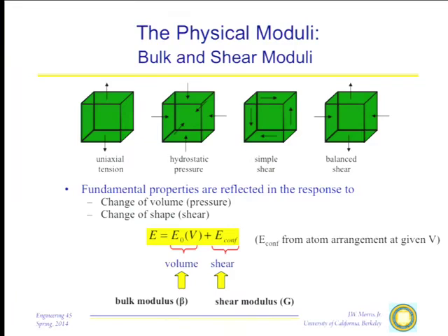When we calculate the energy from first principles, well, some people just brute force it. But if you want to do a relatively simple calculation of the cohesive energy of a solid, you calculate the energy as a function of atomic volume. It turns out that most of the energy that comes from making a solid just comes from changing the atomic volume, irrespective of the configuration. The second thing that you calculate to add to that is the configuration. So I would calculate energy as a function of atomic volume, then I would impose a particular crystal structure and see how that changes the energy. And so I'd have these two terms. Well, in terms of elastic deformation, that is the energy as a function of volume plus a function of shape.